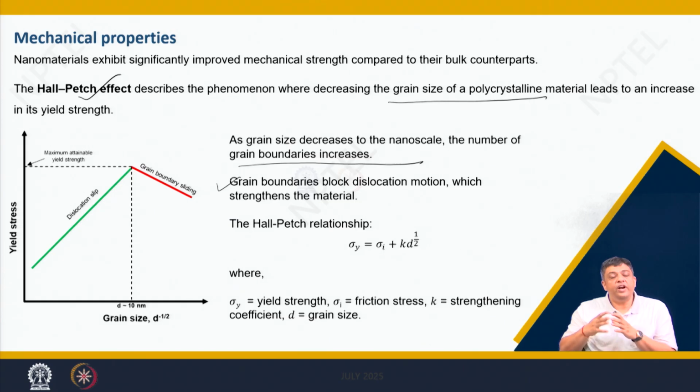Why? For example, if there is a crack which travels through one of the tiles or the mosaic area, then when it hits the boundary, it cannot straight away transfer to the next side, and therefore, the damage is actually restricted. So, that is what the advantage is.